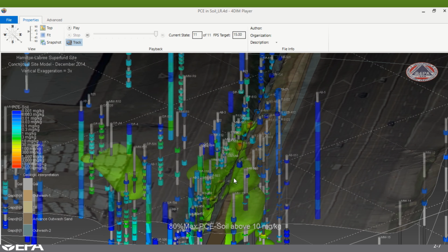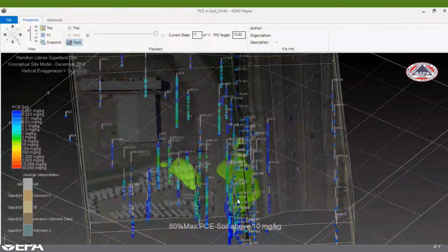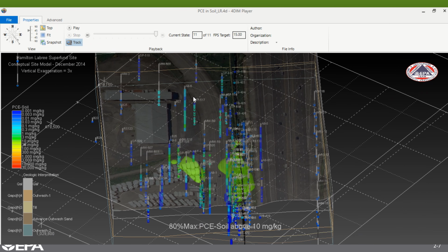and then really go back in and delineate what those soil concentrations look like to help us design what you'll see later as a thermal remedy through this area, and also understanding that there are some higher hydraulic conductivity pathways, some potential soil sorption going on here with higher concentrations of PCE. And when we look at the groundwater data too, you'll see that some of the transmissive zones and some of the plume moving out in this direction. So the thermal will be in here right under Berwick Creek, and then they'll be doing enhanced reductive dechlorination out here in various areas of the plume to try to help attack that, using a combined remedy.